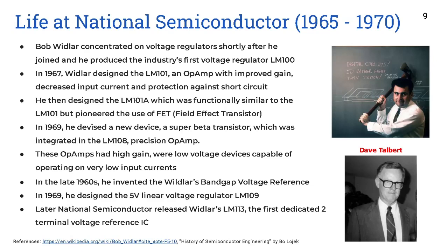So he devised a method in which, by using the band gap in the material, we could generate a voltage reference. The band gap doesn't change with temperature, and it doesn't change with what current is flowing in the circuit. So it provided a perfect reference voltage to be used in voltage regulators.